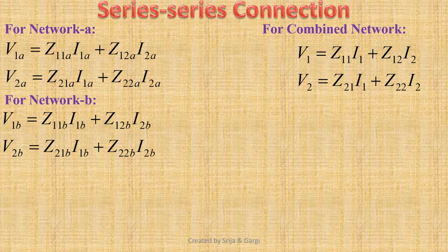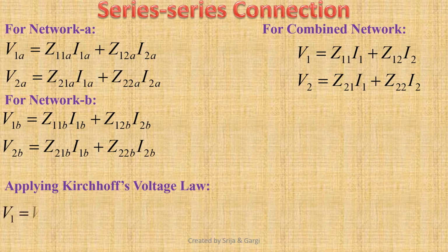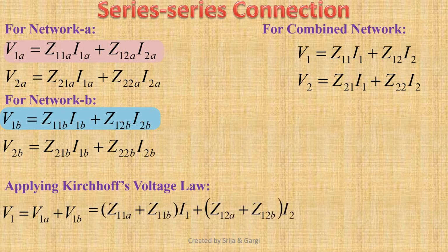As the input ports are connected in series, we can write, applying Kirchhoff's voltage law, V1 equals V1A plus V1B. Using the expressions of V1A and V1B, we get (Z11A plus Z11B) times I1 plus (Z12A plus Z12B) times I2.